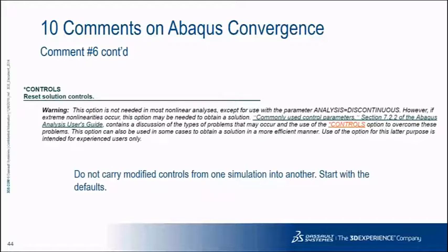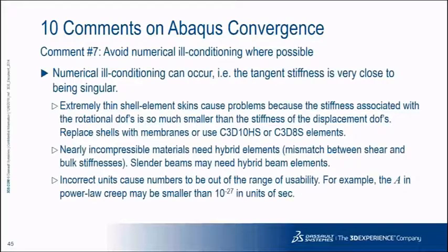So just a warning for star controls. You can see that here if you change them. And comment number 7, avoid numerical ill conditioning where possible. So avoid things like thin shell element skins. You want to use hybrid elements for nearly incompressible materials.